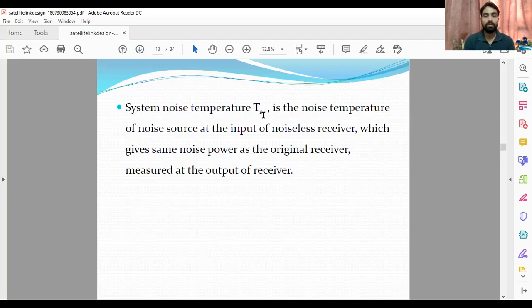So we are talking about the noise temperature. The noise temperature is taken as Tn, which is because of noise. If the noise is being created by the system, it is taken as Ts. And importantly, this is exactly proportional to the power. Knowing the value of the temperature, one can easily go for the calculation of the power. This is exactly important.